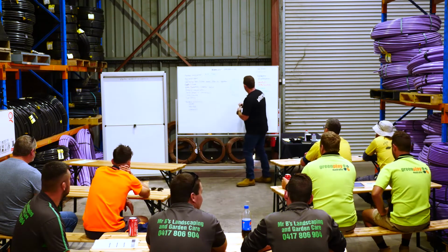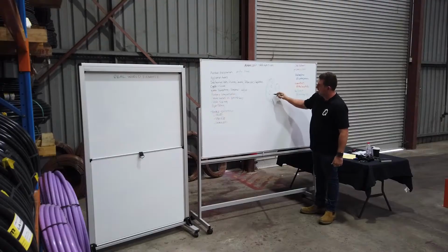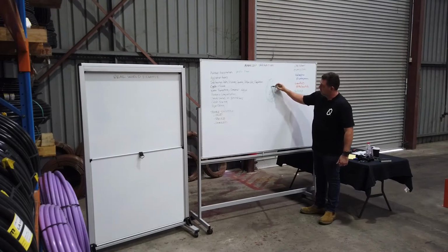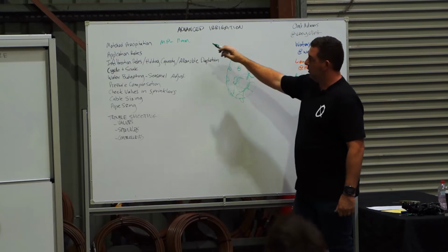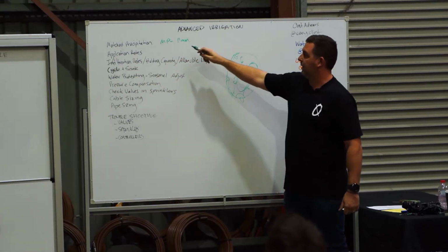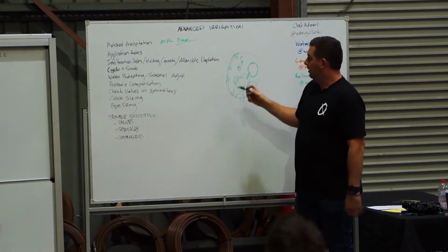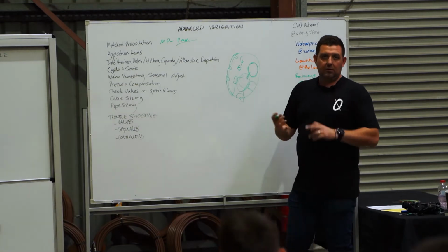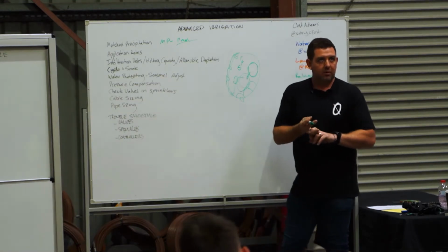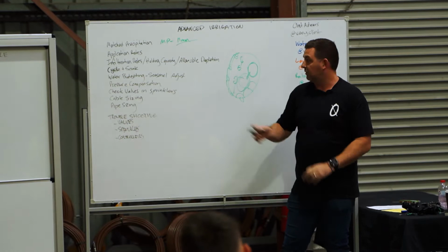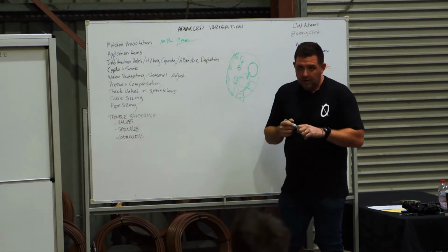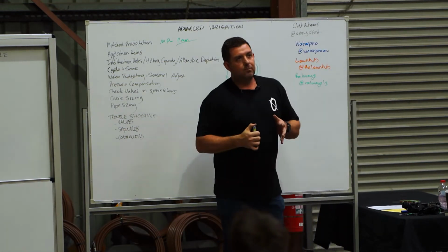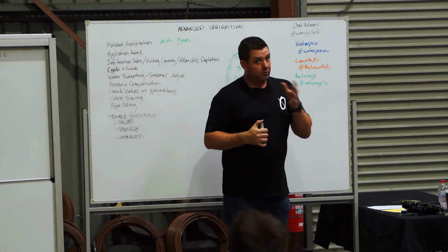And by doing that, you might have a whole lot of water there and then a whole lot of water there, but they're not joining across there. So the idea is that you get your application rate accurately, by using either good irrigation design or products that are matched precipitation, like the MP rotators. The same concept applies for drip irrigation as well.